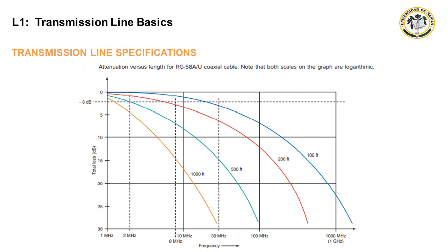When you are considering the relationship between the cable length and attenuation, remember that a transmission line is a low-pass filter whose cutoff frequency depends both on the distributed inductance and capacitance along the line and on its length. The longer the line, the lower its cutoff frequency. This means that higher frequency signals beyond the cutoff frequency are rolled off at a rapid rate. This is illustrated in this slide.